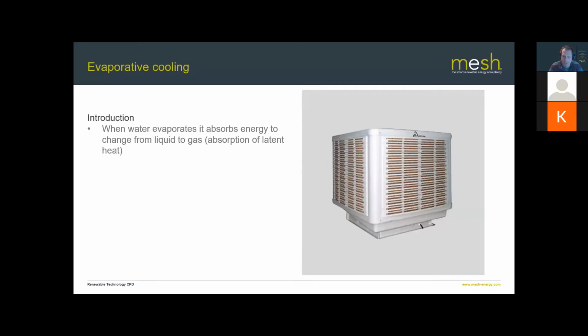All that heat is going into converting liquid water into steam. If you left the kettle running long enough, you would eventually boil the kettle dry. That's basically how an evaporative cooler works: it's changing liquid water into vapor. So the energy absorbed by the water as it's turned into vapor is reducing the temperature of the airstream that's going through the evaporative cooler.